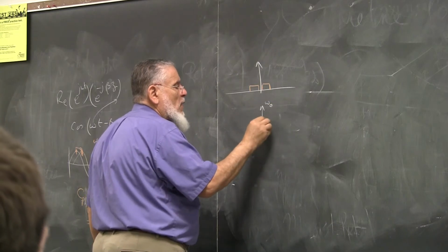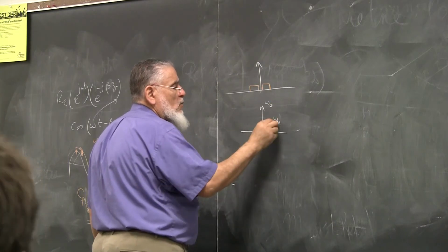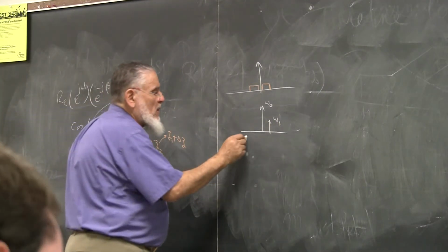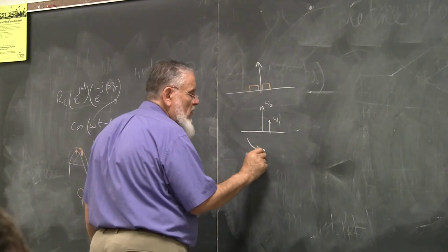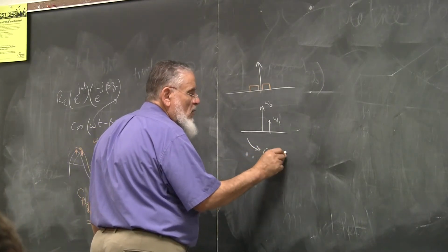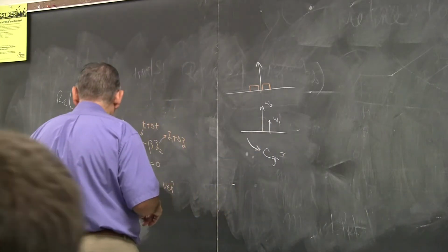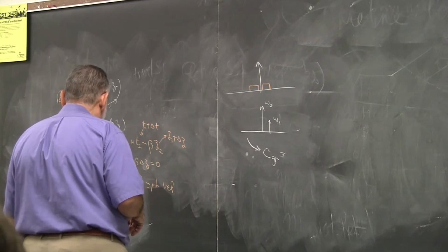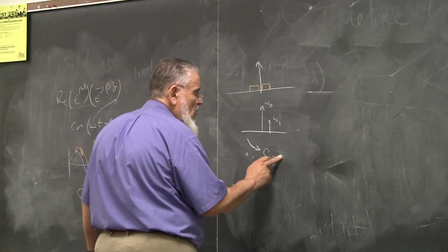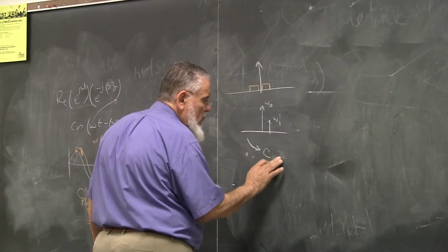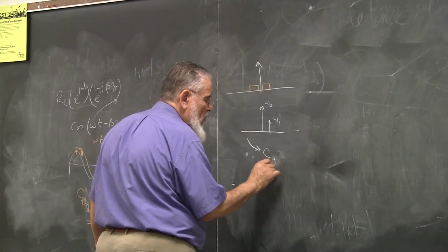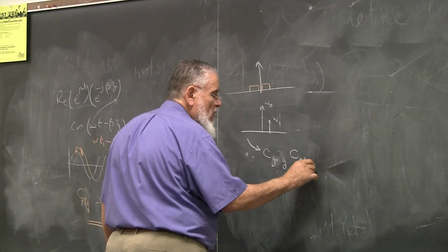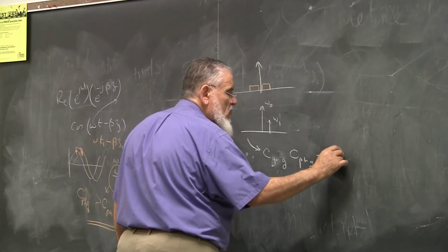All right? So assume now that we only have omega naught and omega 1. Right? And omega 1 here is your information signal. If you develop the equations for that, you'll find that the group velocity, C group, which is the velocity at which this information travels, is the inverse situation here. It turns out to be C group in the guide times C phase in the guide is equal to C unguided squared.